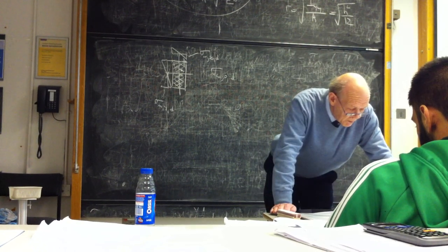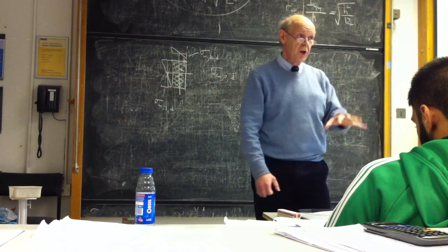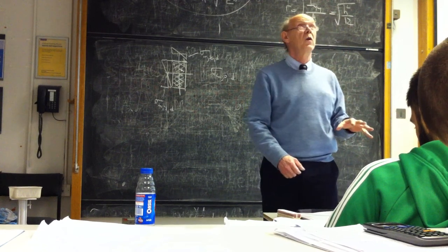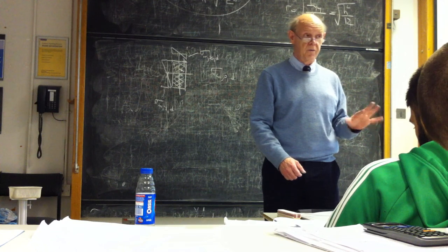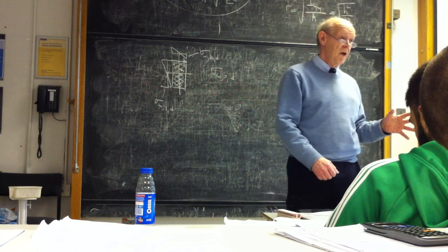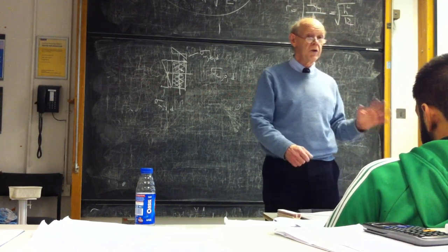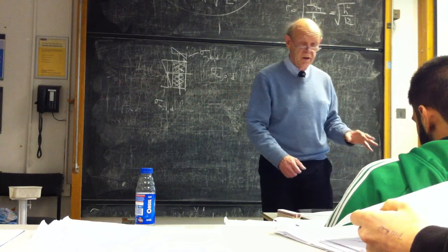Right. You want to obviously compare these, which are the actual stresses that the load causes, with what the material can stand, the permissible stresses, which the Europeans call the strengths. Be very careful about this one. The strength is permissible stress. Strength is in effect permissible stress, yeah. So whenever you see a Eurocode referring to the strength, it's talking about the permissible stress.